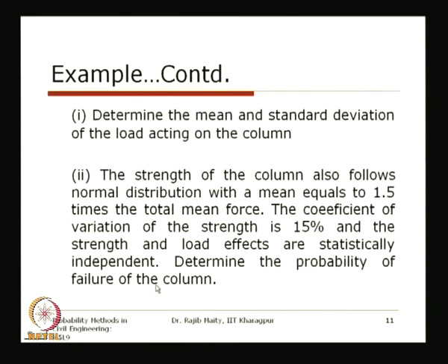Now, to give a little background, the word strength that is being used here for the column means how much force it can resist. So, that has the same unit as the loading. Now, to declare that the column has failed, we can say that if the difference becomes negative, that is, if the load exceeds the strength of the column, at that time we call the column failed. So, you can see that in the first problem we have to go for a summation, and in the second problem we have to go for a difference between the strength and the total load on the column.